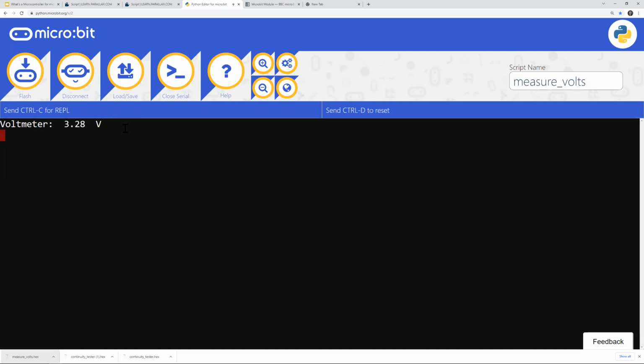Is that normal? Yeah, that may just be still a loose connection, like the alligator clip jaws are not gripping the wire ends quite well enough, or possibly something on the 3-pin headers. But I think you're probably good. And then the thing to do would just be to check the middle columns as well.